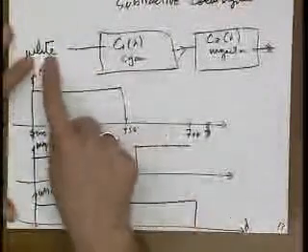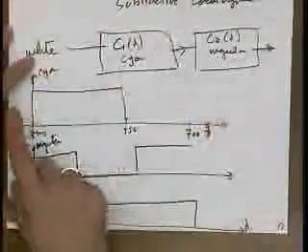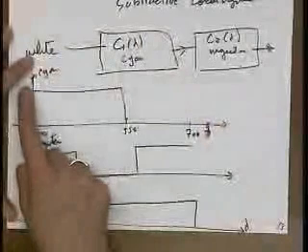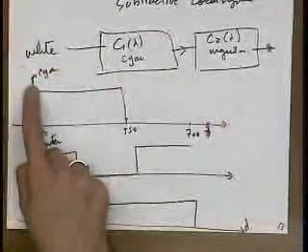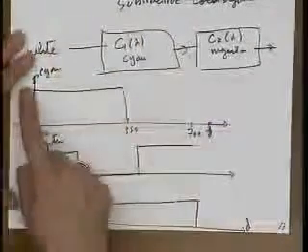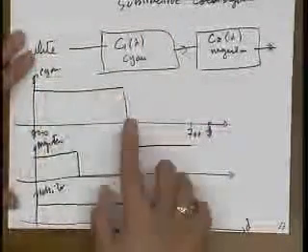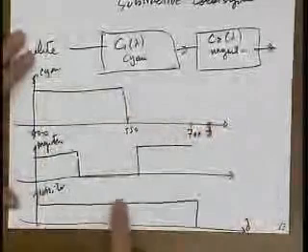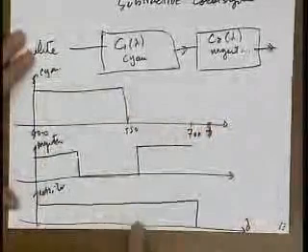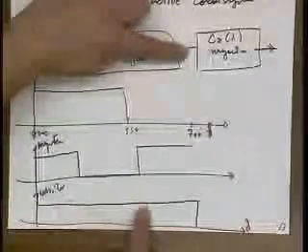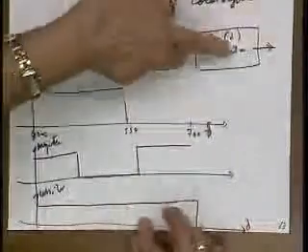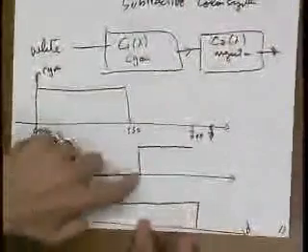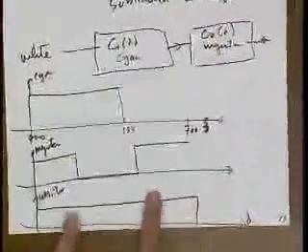And it passes through a filter that lets this piece go through and blocks from 550 to 700. So it keeps this portion. So now at the output here, I only have this portion of the signal. And then I pass it through the magenta filter shown here, and magenta blocks from here to here. So now this part gets knocked out, and all I'm left with is from here to here.